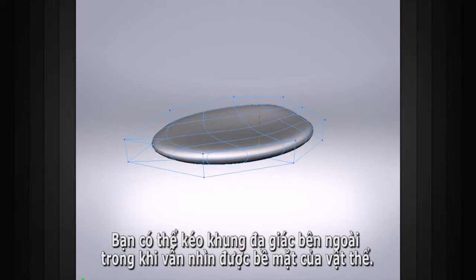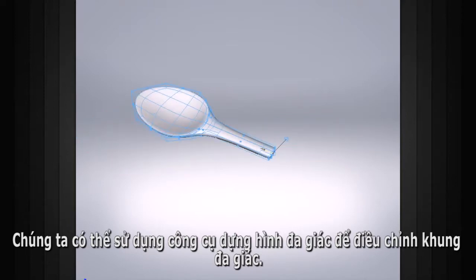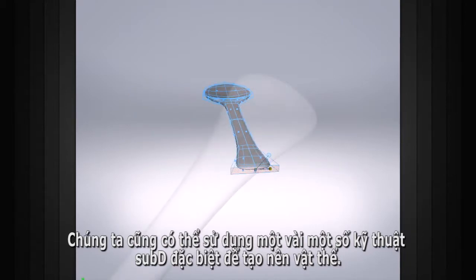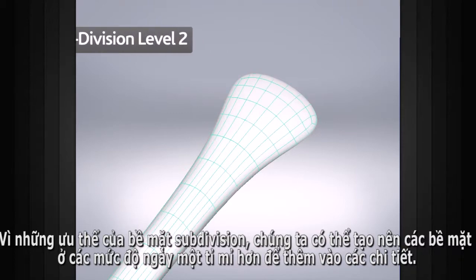While we can use our polygon modeling tools to modify the surface's polygon cage, we can also use several sub-D specific techniques to create models. Because of the progressive refinement of the subdivision surface, we can access finer and finer levels of the surface in order to actually add the detail.